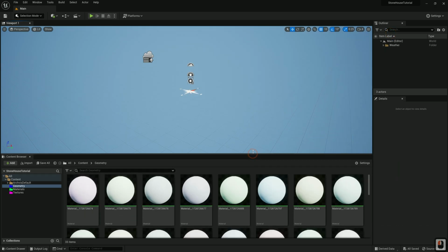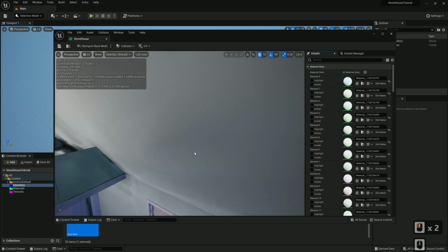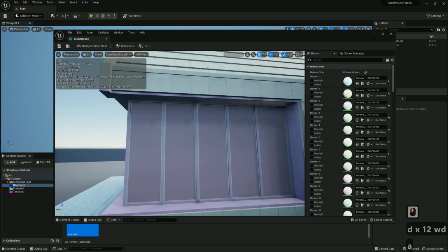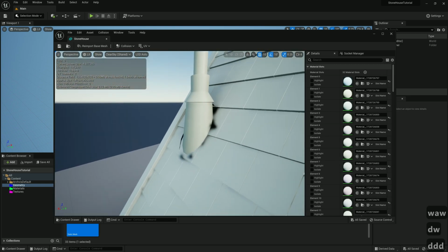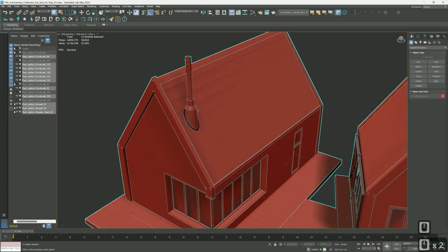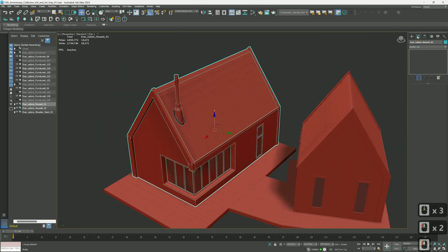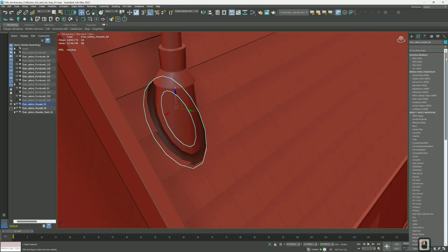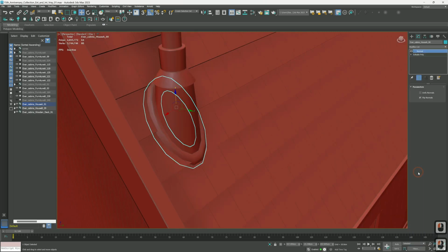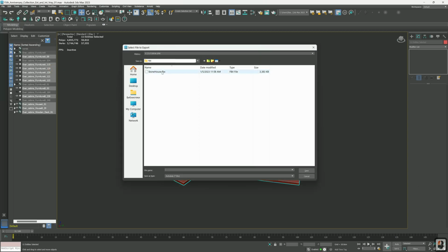Now assets are displayed correctly. Check the imported model. Here you can see that the polygons have incorrect normals. Let's fix this. Back to 3ds Max. Select the element you want to fix and apply the Normal modifier. Re-export the model or overwrite the previous one.